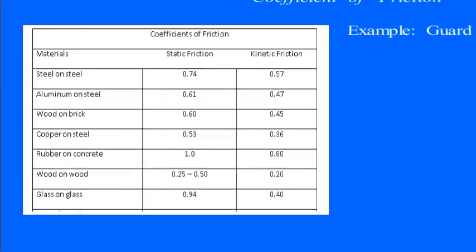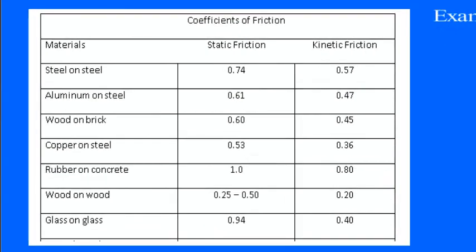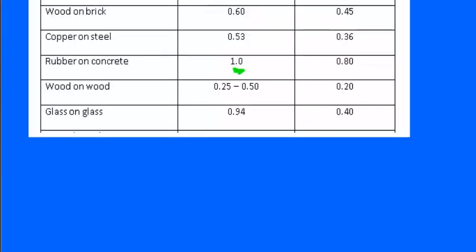And you can see that it depends on which two surfaces, like I mentioned earlier, are interacting. And you notice here in every case that this value is static friction, right? All these values are higher than kinetic. Notice also that a value of 1.0 is very high, right? That means the ratio of friction force to normal force is 1. Remember, the way that we got mu here in the first place is the ratio of friction force to normal force, right? So a ratio of 1 means there's as much friction as the weight of the object. That's huge. Okay.